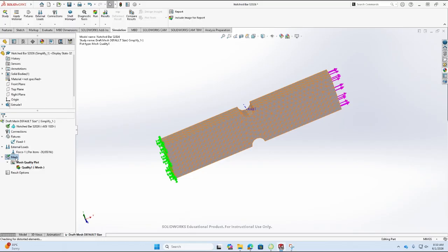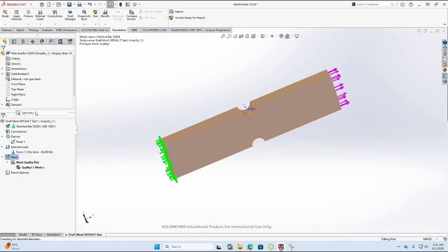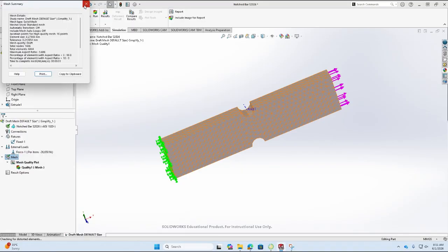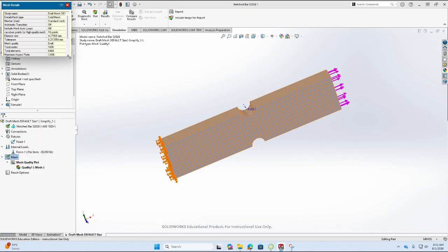This thing which I am going to do is called a mesh convergence study. So basically in finite element analysis, as we change the mesh, the results will change, and we need to have an idea about when the results have suitably converged to a unique value, okay. I will take you through this process step by step, but for the first mesh, I have to go into the summary option, or actually if I use detail, I think it's easier to read. So if you go into the detail option, you can see this table, right? The table lists all the key things about your mesh.